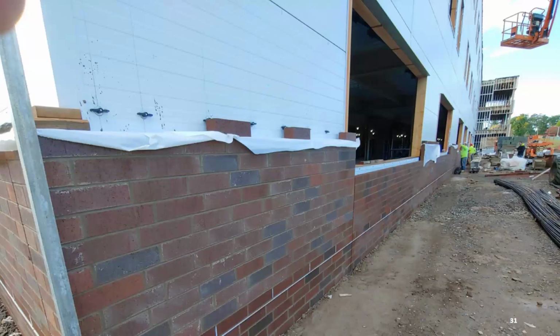And you will see we have the exterior brick that's being put on. The brick ties would go into the building, fasten through, and go back to the structure. And then the brick can be installed. And then you'll see as this building grows, the other materials that are used.